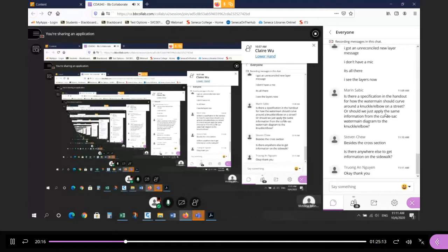So that's its approximate location. I don't want to do any more with that because what we're going to do with it is really an AutoCAD exercise, and I'm not going to waste your time now. We're trying to concentrate mostly on Civil 3D functions. So just put it behind the back, into the boulevard, as an offset of 1 meter, and just leave it there. Don't do anything else.